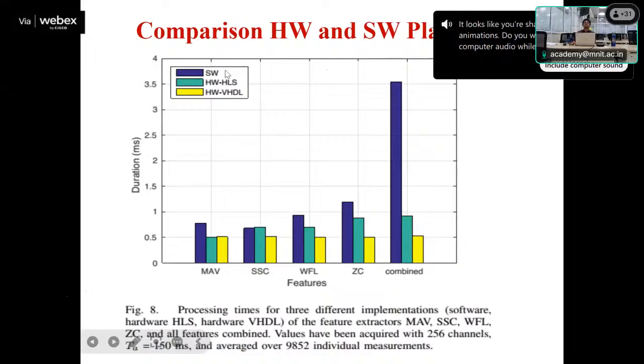So that is the hardware HLS, and there is a pure VHDL approach, where everything is written by me and implemented on FPGA. You consider it a full custom design, because when you use the HLS model, the conversion is possible. Your C code can be converted into VHDL, but the syntax is basically machine interpreted, and it is not exactly optimized code.